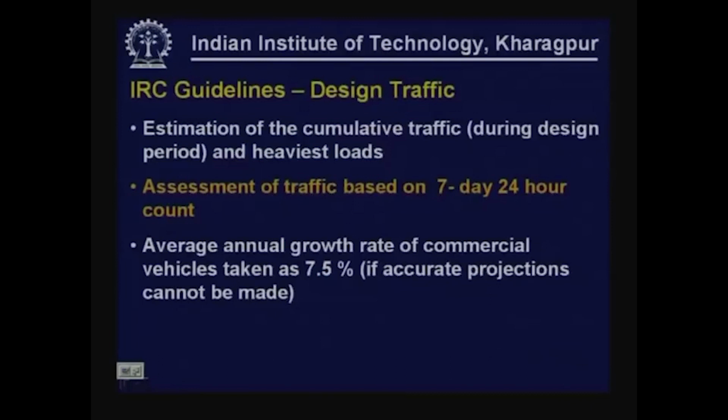Assessment of traffic usually has to be based on a 7-day, 24-hour count. Obviously, we have to make traffic projections for the future, the next 25 or 30 years of design period, but this has to be based on the traffic counts that we make in the present situation for a short time period. So, this has to be done for a 7-day continuous 24-hour period.